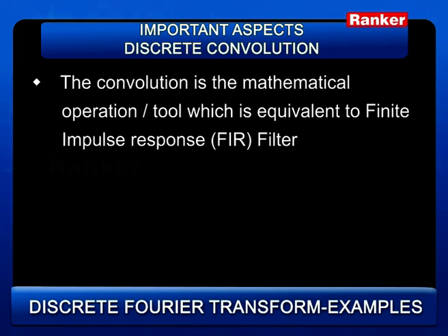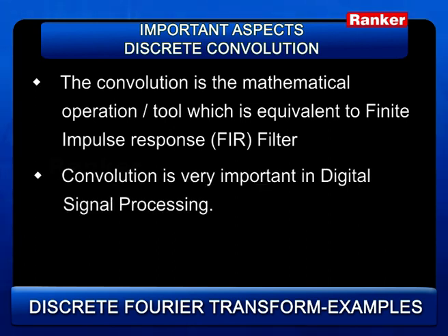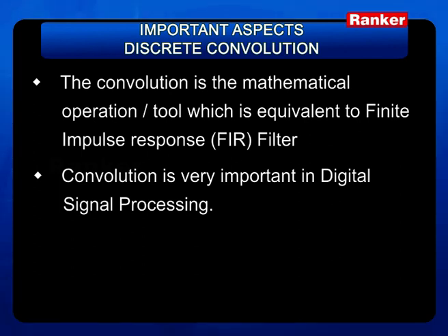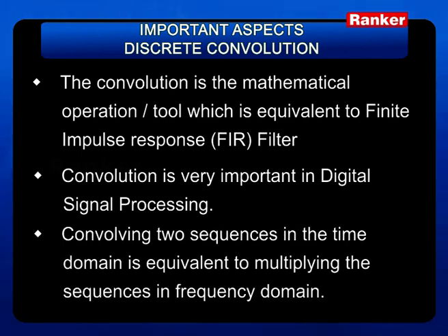Okay, it's a mathematical tool which is equivalent to a finite impulse response filter, FIR filter. Convolution is very important in digital signal processing. Convolving two sequences in the time domain is equivalent to multiplying the sequences in the frequency domain. This we are all aware of.